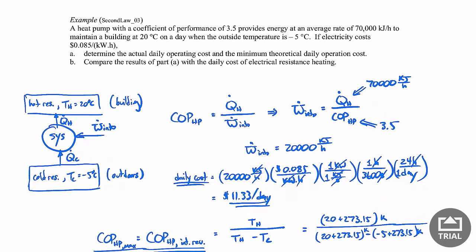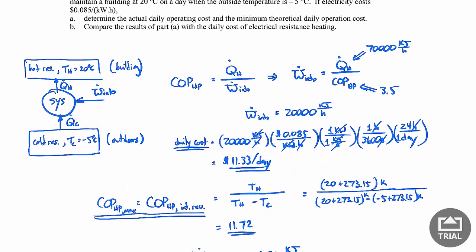And the way that we move that energy around, it all has to do with the system in here. We're taking our refrigerant in the system, and in this particular region, the refrigerant's very cold, and so we get heat transfer into it, and then we do some processing to it, and then when it gets to this region, it's hot, and we offload the energy into the hot reservoir. So that's why it's much more efficient to actually use a heat pump than an electrical resistance heater.